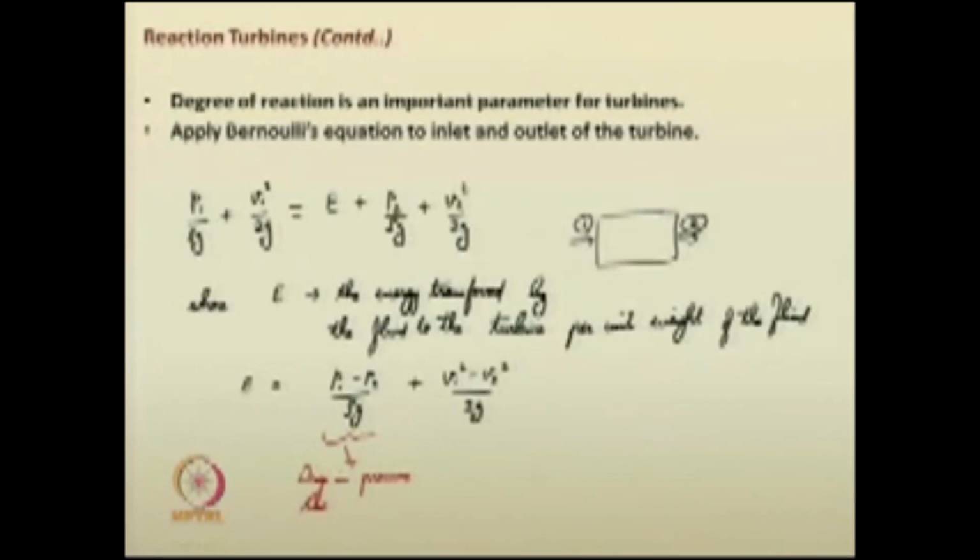Let us consider it as the pressure term, the change in pressure or drop in pressure, and this particular quantity is the drop in velocity head. So, the energy transferred by the fluid to the turbine includes change in pressure as well as change in velocity head.